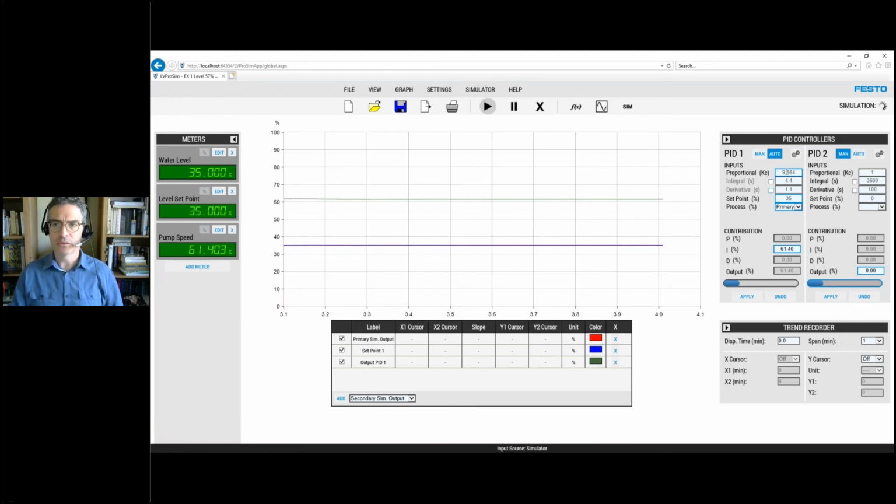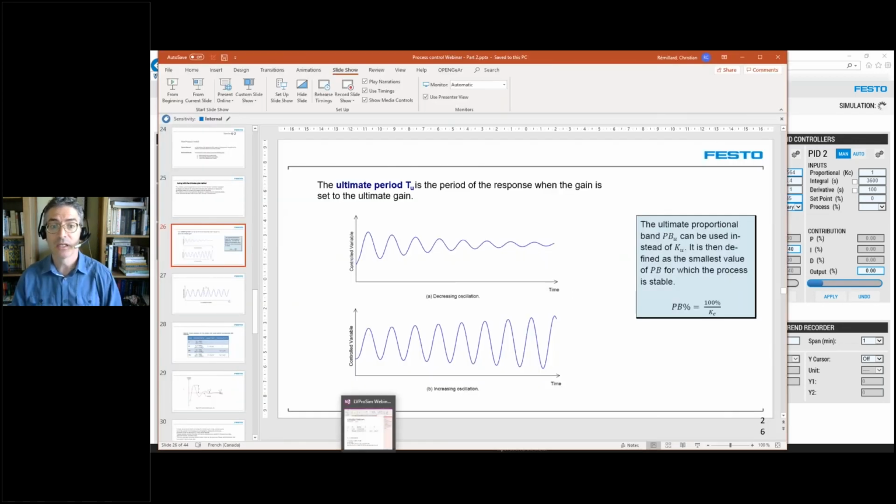And we will do just like we were doing with the trial and error. We will start with a low value of the gain and multiply it by 2, multiply it by 2, multiply it by 2. But we will do that until, instead of having a proper response and before oscillation, in fact, we will keep multiplying our gain until we get into full oscillation. So that's the goal of the ultimate cycle. We will keep increasing our controller gain until we get into stable oscillation.